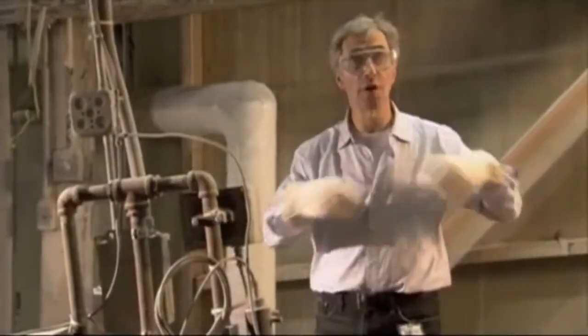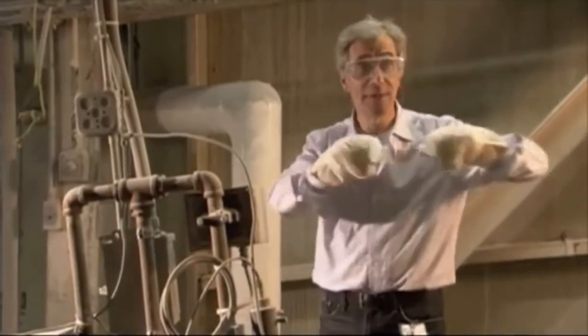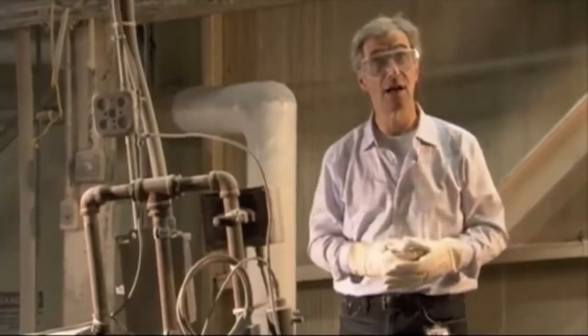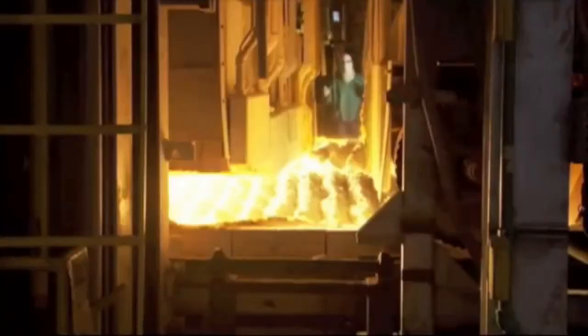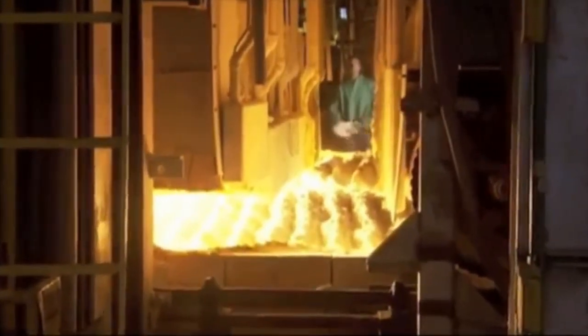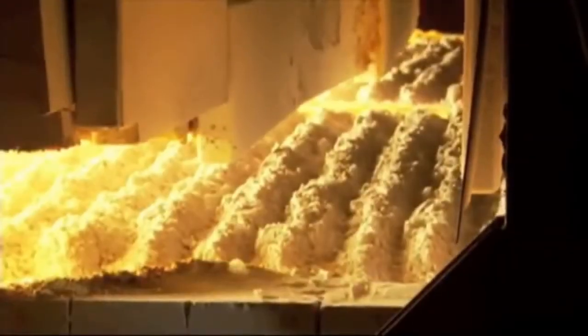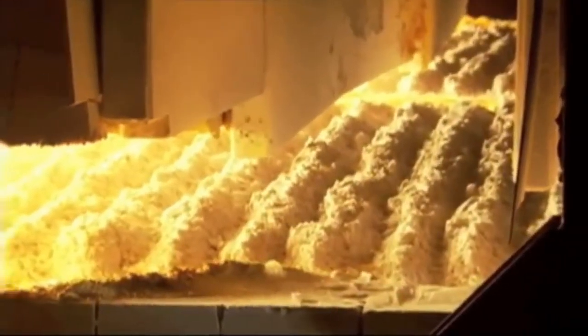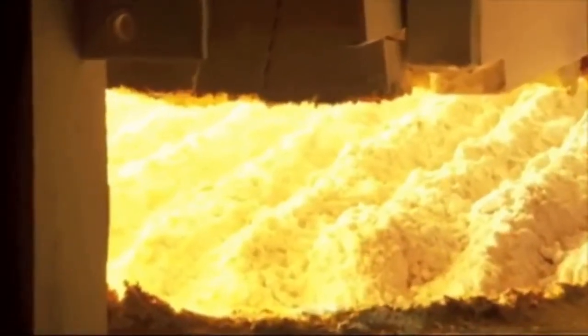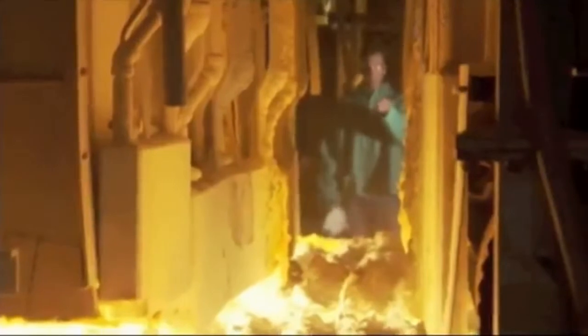These chemicals soften the glass. They make it easier to melt, they terminate the silicon-oxygen chains, and make a more manageable glass to work with. And that soda lime silica glass lies at the heart of every window. Now, all of our raw materials have been mixed together and dumped into tanks like these, where it's a cool 3,000 degrees. It's actually hotter than molten lava. And it will take 3 days for a single molecule of sand to get from this point all the way to the other end of the factory, where it actually starts to resemble a sheet of glass.